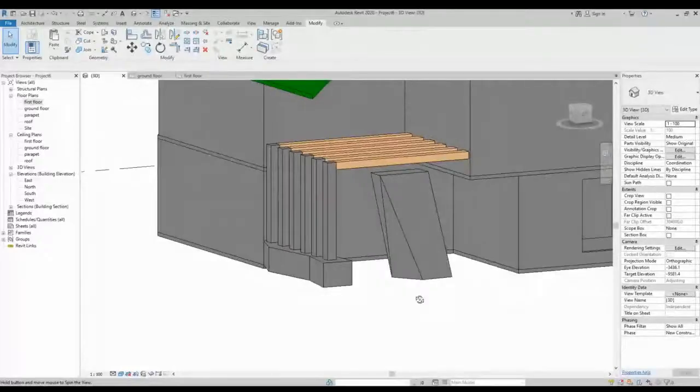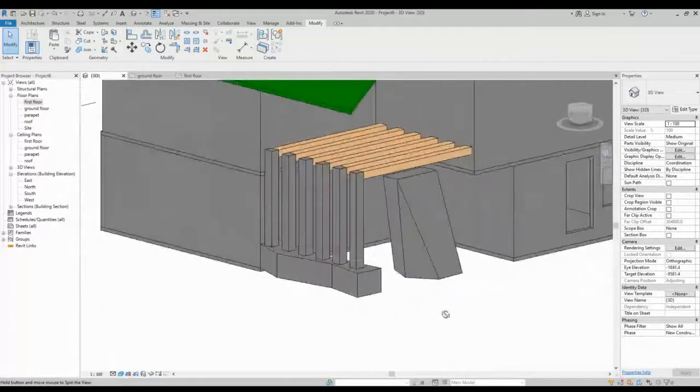You can always go to the plan itself and make sure that you're drawing in the correct position. So I'll just move these and keep it here, for example. Okay. So after you're done, if you want to edit the base again, you click on edit base and move it. If you want to go back to edit top, you can go back to edit top and so on. Okay, when you're done, you click on OK, and it will give me a blend. You can change the material from here if you want. Click on OK, and it will give me the result.